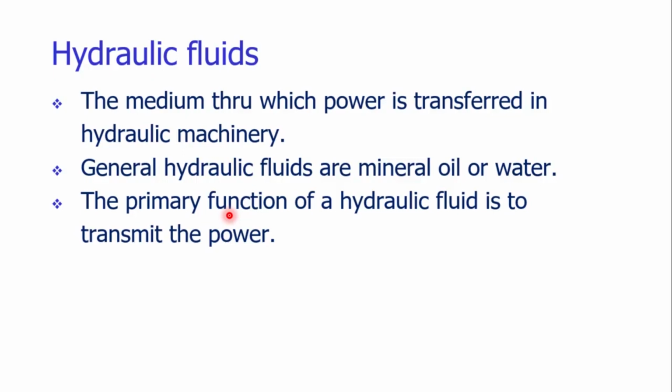The viscosity of the water is also a concern. The viscosity of the water is low, so we need a slightly more viscous fluid. For that purpose, mineral oils are the best choice to be used as the hydraulic fluid.